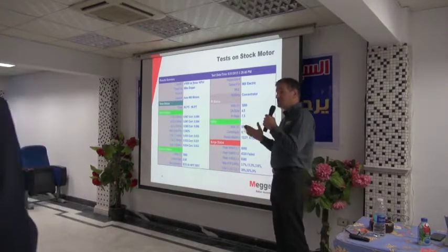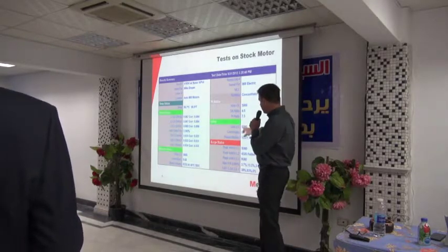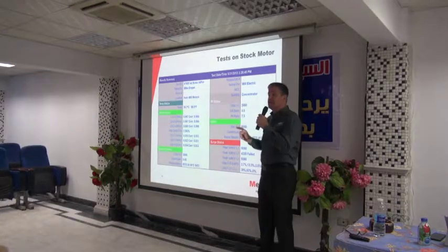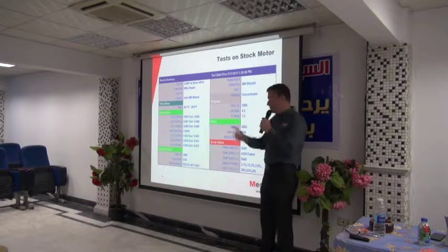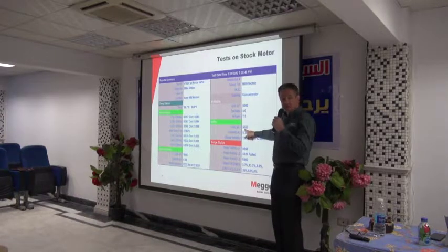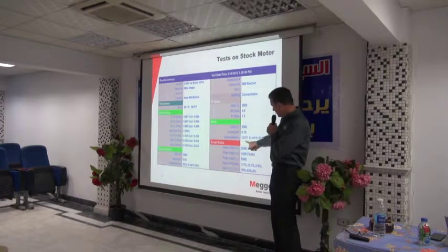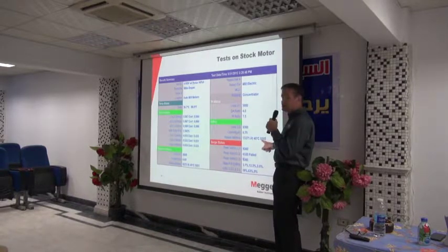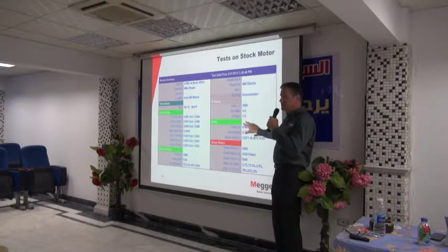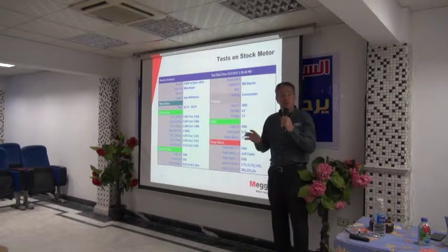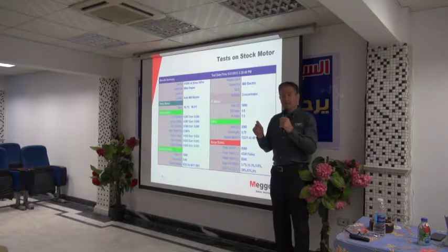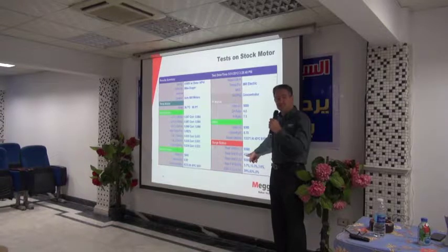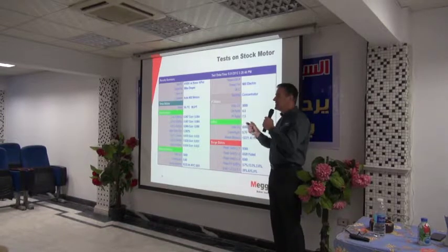Okay, so what I want to show you, the most important thing, the customer tested the motor. The motor is 4,160. He tested the motor at twice the rated voltage plus 1,000. This is the standard. And he had 13,000 megaohms, or at 40 degrees, 8,000. Okay, so at 9,000 volts we saw no problem with DC voltage. But when we performed the surge test, we saw a problem at 4,000 volts. Because the tests are different.